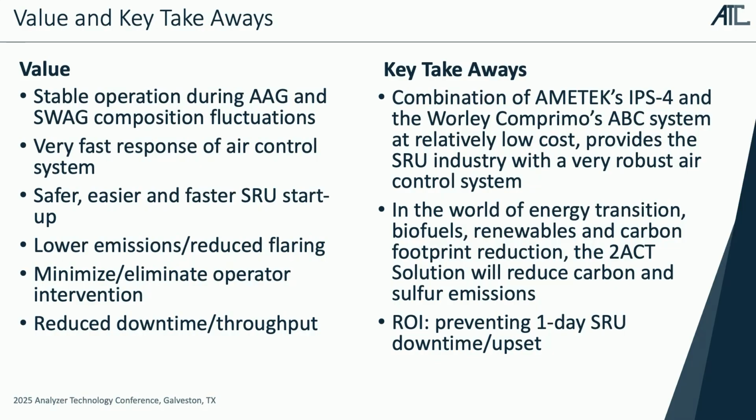If a plant is restricted in capacity, or in case of an upset or an emission violation would have to reduce in capacity in the refinery or the gas plant, then the cost of that is significant. And in such a situation, the return on investment by installing a fairly straightforward feed-forward analyzer plus control loop is pretty fast, could be as fast as a day.